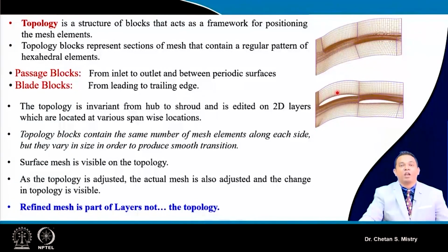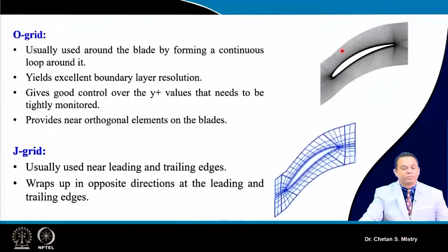Now we need to be very careful: refinement of mesh is a part of the layer. So we will be doing refinement, or changing the size of the element, everything within these blocks. It is nothing to do with the topology. Be careful about this part. Now, once we have made this block or topology, what will be our next step?